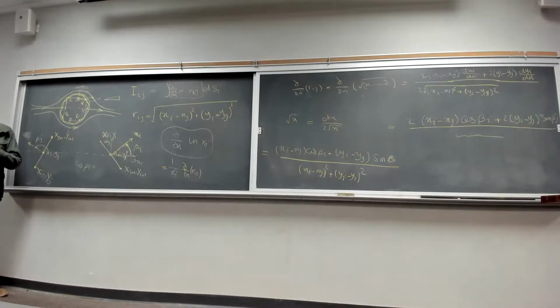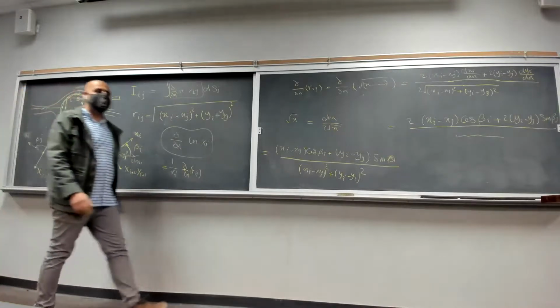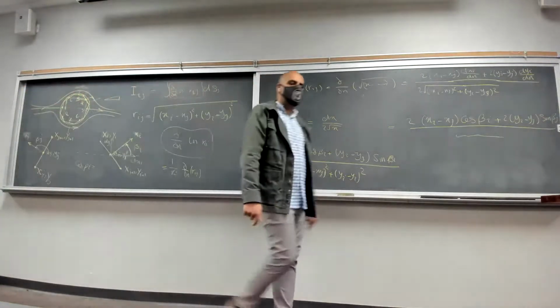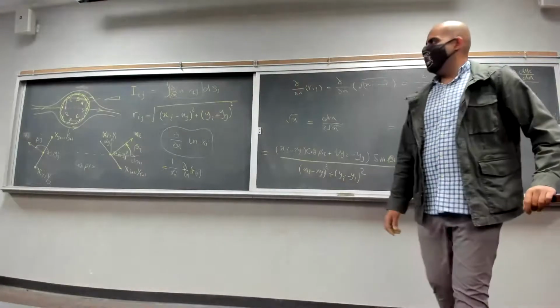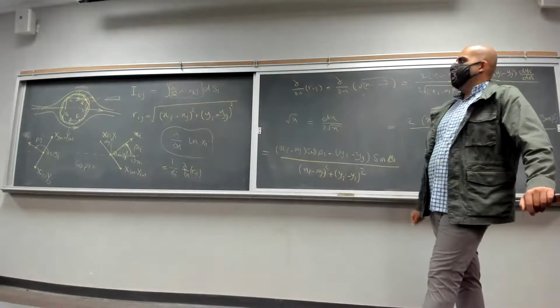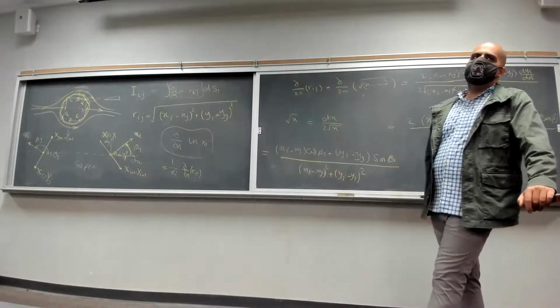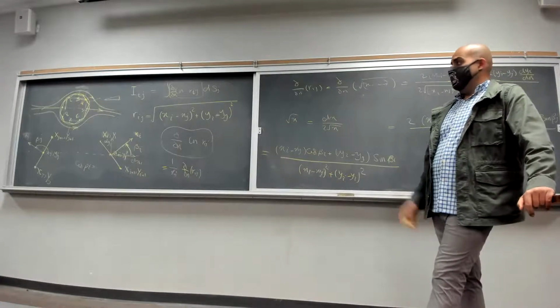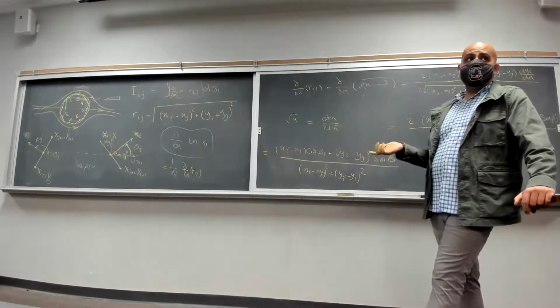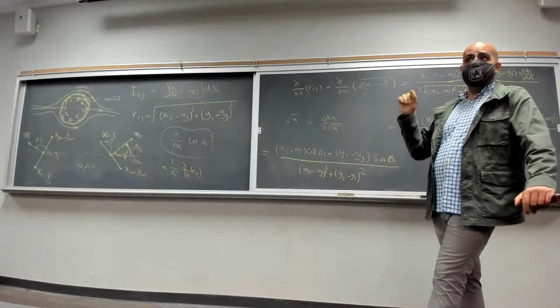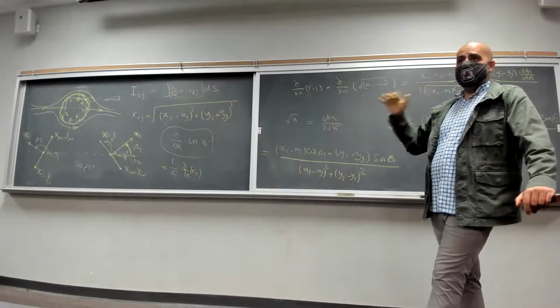You will have one equation with 8 unknowns, 8 lambdas. Then you write the same thing for panel 2, 1 equation, 8 unknowns, until you have 8 equations and 8 unknowns, and you can solve that system of equations. But here, your homework problem is actually easier. You have to do this for 4 panels, which makes everything much, much easier.